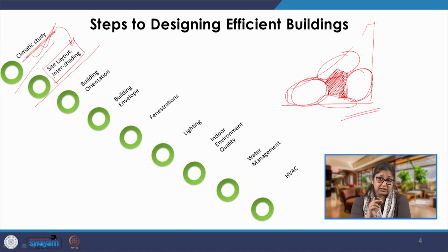In addition to energy, at this level itself, at the second step itself, we also need to take into account the drainage, which is primary. Unfortunately, we have stopped looking at drainage as part of the larger region. We think that my problem is just this site. So, what I will have, okay, my site is like an airtight container, and the water outside my boundary is not my problem. So, I will only design my drainage for the amount of water that is going to be here. Now, what about the water that is going to go on the street or the water that is going to come from the street to us?